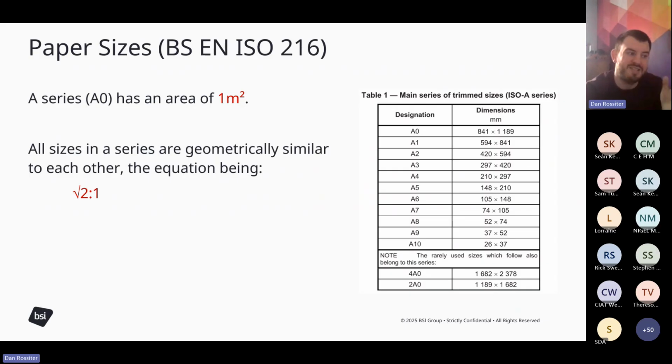And you'll notice that that same ratio is used in a number of places. It's used in line weights and it's used in drawing pens. Because if you look at your drawing pen sizes, it'll go 0.18, 0.25, 0.35, 0.5, and it has that same relationship. So by going down a drawing size, you effectively go down a font size or a line weight, and it remains perfectly consistent.